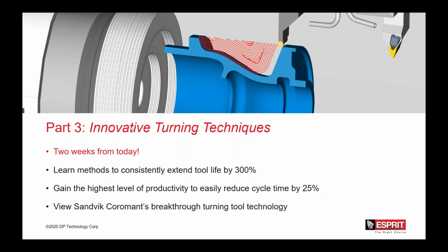So there's one other Sandvik question here. It says, after the dwell at the bottom of a drill, can we stop the tool, reverse the tool on the way back up to prevent tool wear? My response is no to that. I'd like to confirm that with Jim too, though. Yeah, I've not seen that have any favorable effect as far as reversing the rotation of the drill. No.